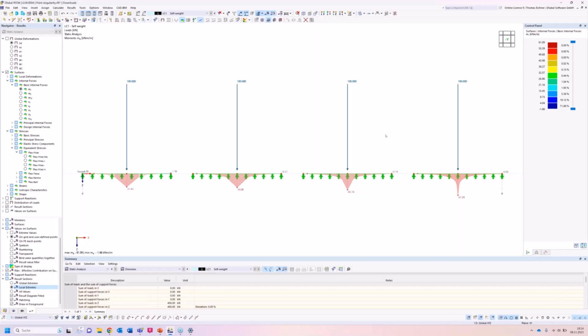Means if you design now for this value of 37, you could be underestimating the internal forces. And we can inspect 37 to 61. There's almost like a factor of 2 between those. So that's a real problem, since how should we know how much reinforcement we should put in that area? How should we know how to design this singularity?